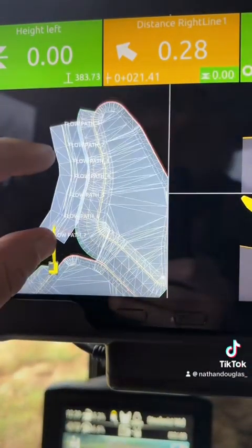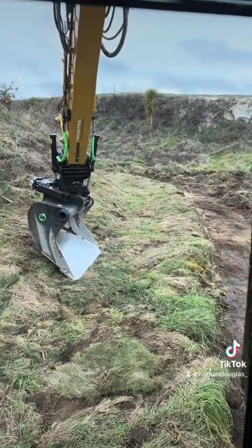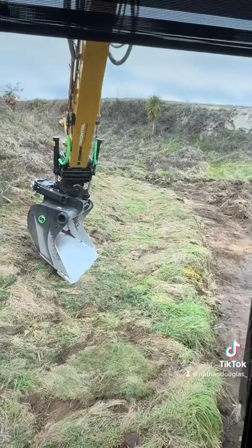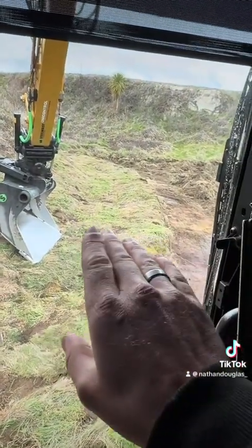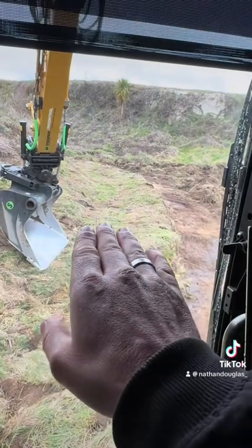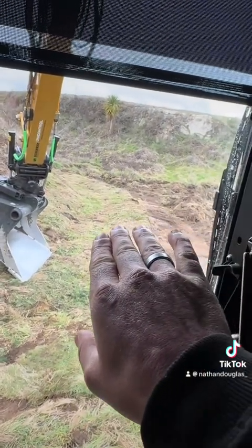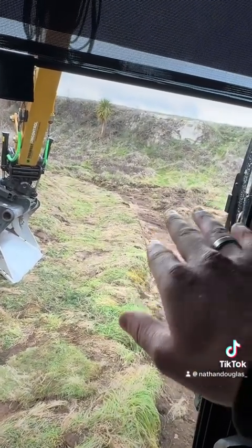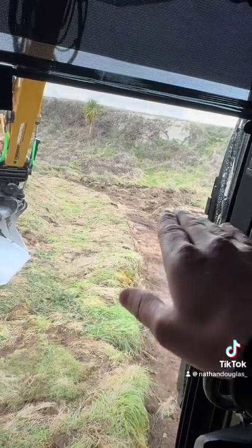This is the design. That's the design all covered in grass the whole way. So I've laid all of this grass on the edge here. It's a bit hard to tell with the grass in it now, but it batters down. There's a flat of 1200, and then it batters back up, and then I've designed that there so that'll just run once this is built up with pumice. That edge will just go straight across and build straight into the top of the basin.